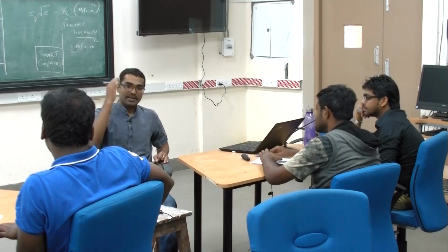So they said you could certainly think about blowing relevant gases. That could be dinitrogen or various inert gases. Another thing is, they said you can add some agents that decompose to give rise to gases having very large specific volume. Hydrogen has the highest specific volume. So let us think about something that is hydrogen evolving. TiH4 was one example, or TiH2. You heat it along with the melt beyond a certain temperature. It comes apart and hydrogen evolves, and eventually the bubble created by hydrogen can be frozen in when you cool it down, right? So that was another idea that they gave.